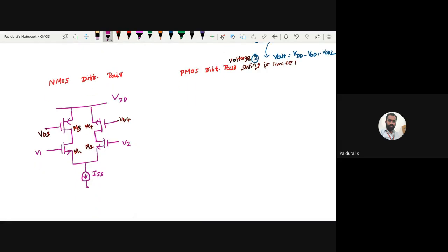Let me draw its equivalent next to this, just one side. Actually, how would this have looked? This is my NMOS differential pair. Here actually it is my RD, this is VDD, right? This is my V1. I have drawn the half circuit. The remaining you please sketch by yourself. And I replaced this by the current source, right? So far any doubt? Similarly, how will the PMOS look?